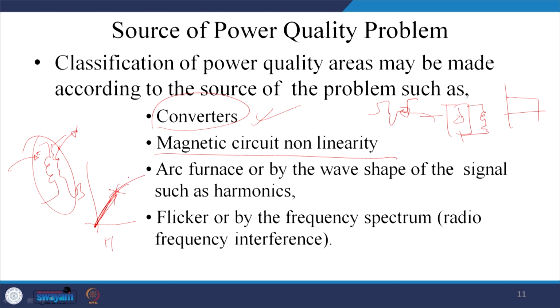If it is unloaded, then you will find the current a little peaky, because demagnetization does not occur, and this is the problem of magnetic circuits as the transformer goes into saturation mode.